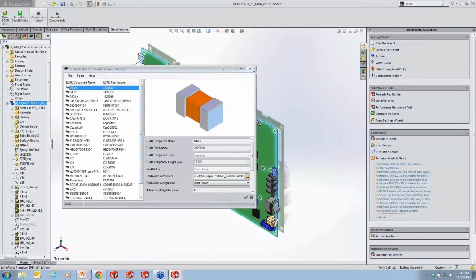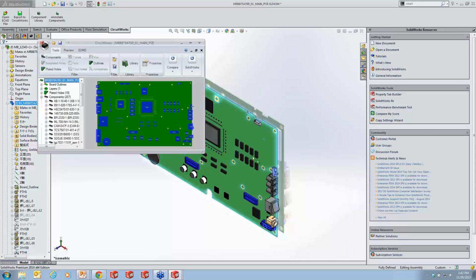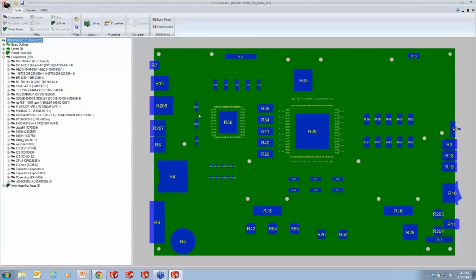And once it's done, it will then open it in CircuitWorks, and I could save it back out and even send it to our electronic engineer that might use it to help make traces. If I'm highly involved in placing components to make sure that the casing that I'm designing fits around it, I might give them some basic component placements and then see if they can utilize that to design the traces and all that. But if I open that in CircuitWorks, you'll also see that there's a few enhancements to CircuitWorks.